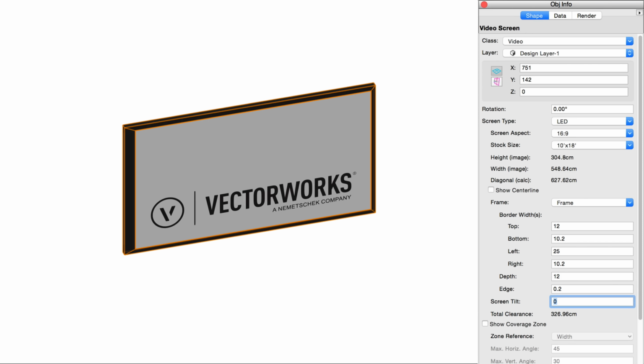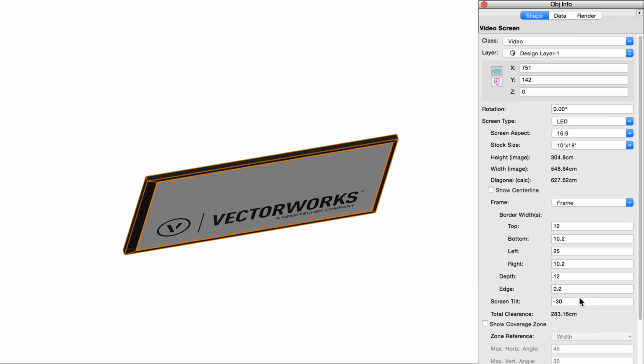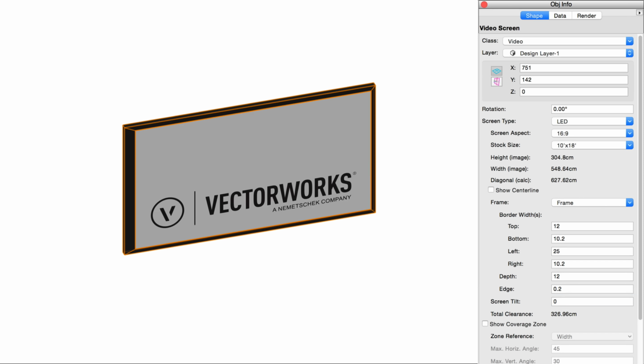Screen tilt allows you to tilt the screen towards or away from its default configuration. Positive values tilt the top of the screen away from the viewer, and negative values tilt it towards the viewer. Total clearance displays the total vertical clearance height required by the complete video screen object from the floor to the top of the screen, including any border, dress kit, valance, or other accessories.